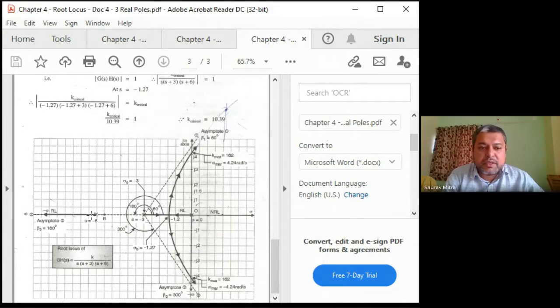So this is the locus of one root. Whichever root is at -6 at k equal to 0, if you increase the value of k, this root will keep going deep into the negative real axis: -6, -7, -8. When k is equal to infinity, that root goes to -infinity. It goes like that; this is a characteristic of the system. Now there are two other roots.